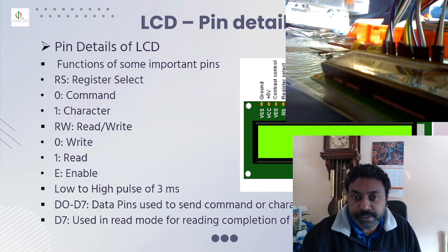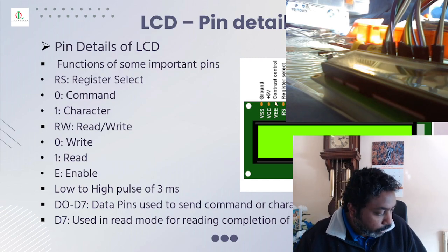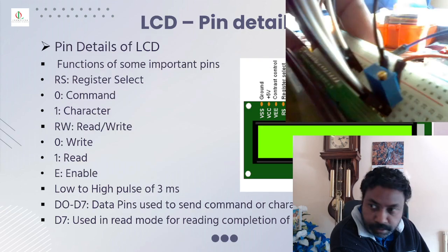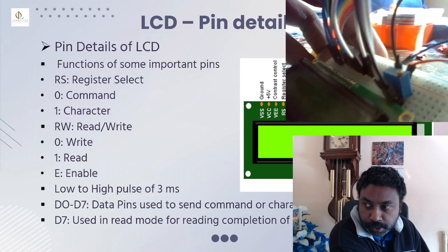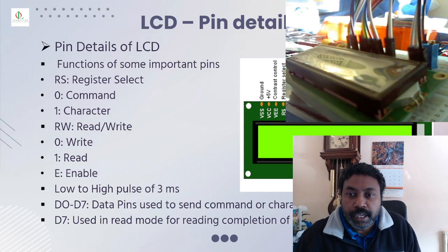The first pin is the ground. Then there is the VCC, that's plus 5 volts, and the VEE is for the contrast of this display and the backlight. So that has to be connected to a port, as you can see from this, the blue port. Yeah, so that's connected. And you've got 3 control pins.